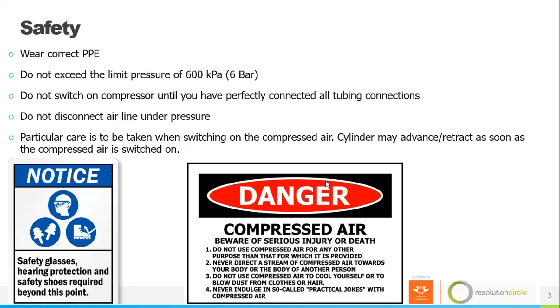The PPE that is required for you to work in that section is safety goggles, earplugs, and safety boots. Since we know that anything can happen, it's best that if something falls from your workbench, your foot is protected against any potential hazard or harm.